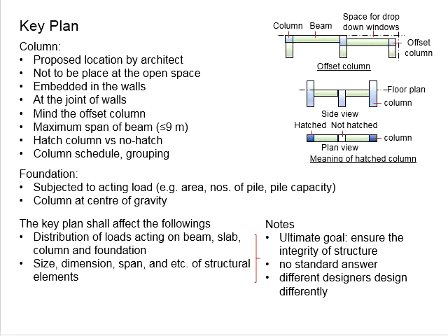And then next, you need to be mindful about the column schedules. Normally on the practical considerations, you need to limit the number of types of columns in the structures. You know that based on your calculations, every single member has its own reinforcement, but you have so many columns in the structures. For a typical terrace house or typical commercial buildings which are attached together in several units, the number of columns can easily reach 100 units. Imagine you have 100 column designs in the key plan.